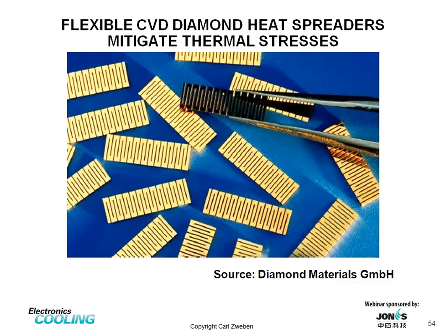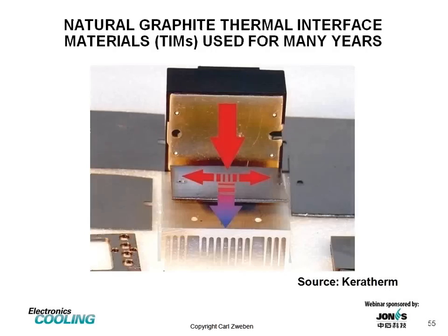So here we have a product made by Diamond Materials in Germany, and they have placed cuts into the CVD diamond to make it flexible, and that has the effect of reducing thermal stresses. So there are ways to get around the CTE mismatch problem.